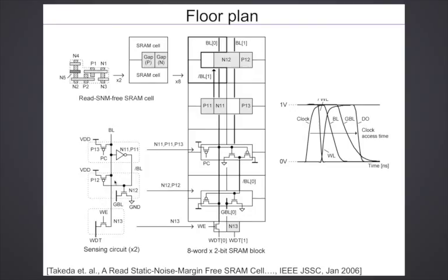So this is like a dynamic circuit. Whenever you have floating nodes in dynamic circuits, they are weakly connected to VDD so that they are not fully floating. So this P12 is a weak pull-up. You have to size it carefully. The design of weak pull-ups or weak pull-downs is a tricky problem. Because what you want is, if there is indeed a 0 in the cell, the pull-down happening in the cell should overpower the weak pull-up. And you have to ensure that happens across all process conditions, and so on. So it's a very difficult and tricky design to make it work.